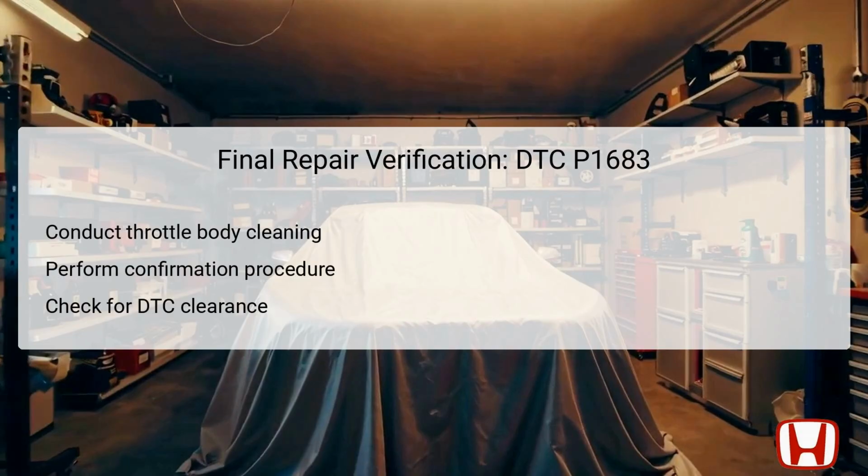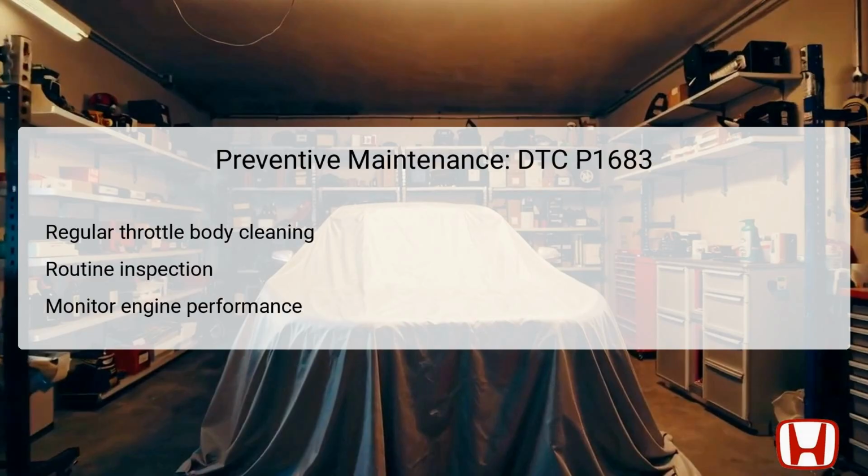Preventive maintenance is key in ensuring the longevity and optimum performance of the throttle body system. Regular cleaning of the throttle body should be scheduled, as this will help prevent carbon buildup that can lead to throttling issues. Incorporating a routine inspection of the throttle valve and the surrounding components can allow for early detection of any developing problems, minimizing the risk of future DTC occurrences.